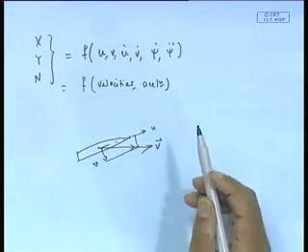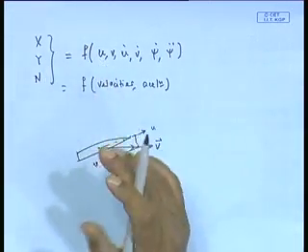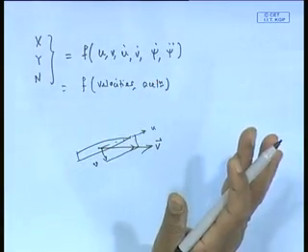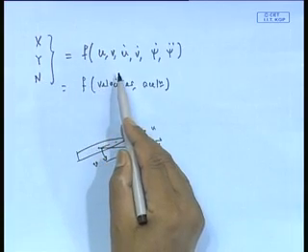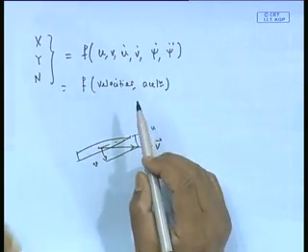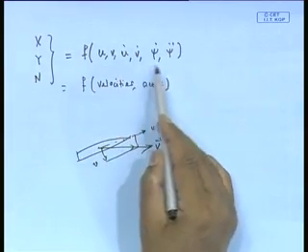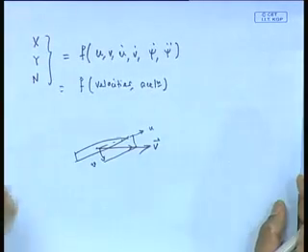So what it means is that these forces will be necessarily a function of all the velocities and all the accelerations. They will depend in some sense. Okay, that is the most important point first we understand. So this has to be understood, that these forces, maneuvering forces and moments will be function of all possible velocities in a general sense, linear velocities, rotational velocity and accelerations. Now this we keep in mind, and now we will see how we can have a so called Taylor expansion type thing.